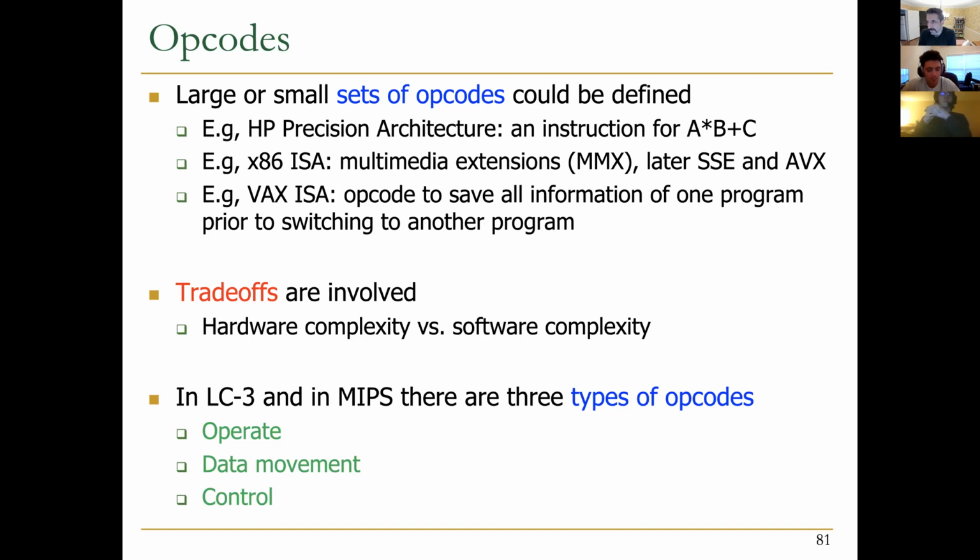there are a lot of hardware accelerators exploiting a particular architecture called systolic arrays, which has been invented many years ago, but now became much more popular due to the benefit that this type of architecture provides, for example, for matrix to vector or matrix to matrix multiplication, which are the backbone of machine learning type of systems.